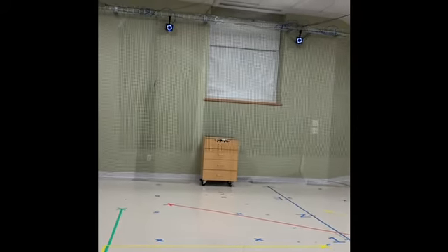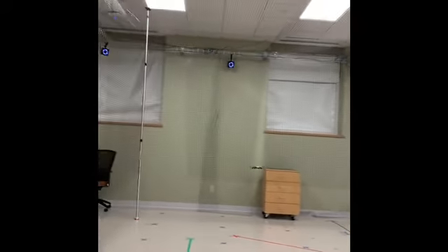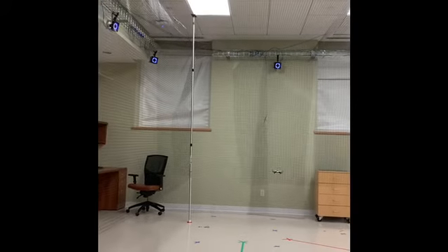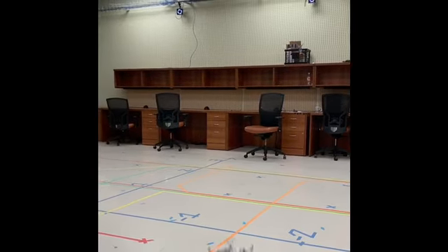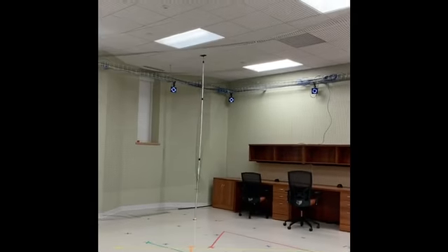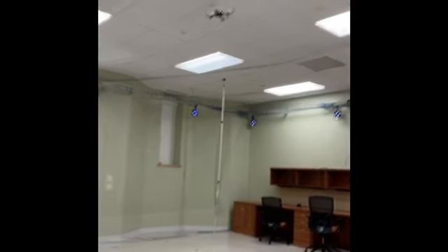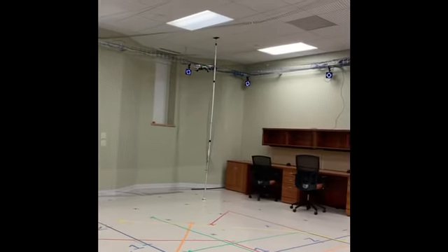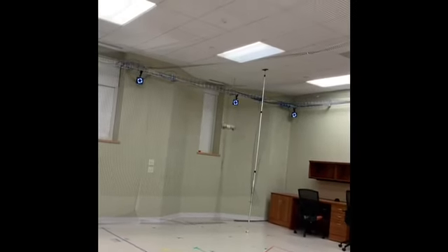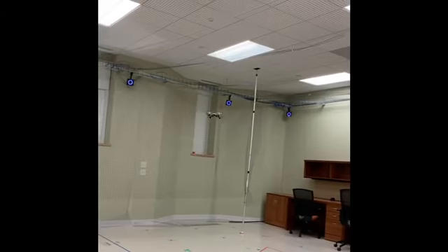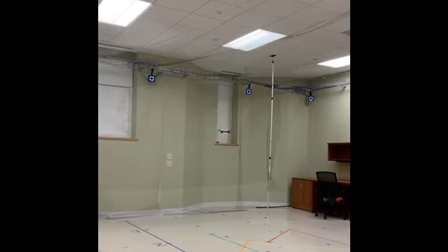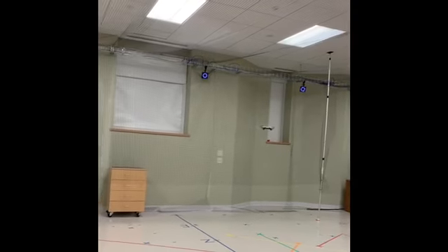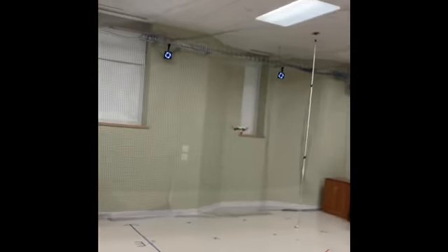As you can see, there is a large height overshoot during takeoff and drift in the X and Y axis during steady state hover. To fix these issues in drift and oscillation, we retuned the gains for the elevator and aileron linear quadratic regulators by adjusting the parameters for each of their respective cost functions. In addition, integral feedback control was added to the elevator and aileron control systems to help eliminate drift of the UAV in the X and Y axes. Overall, these changes helped achieve a very stable hover around 10 seconds into the flight, as the UAV tracked a